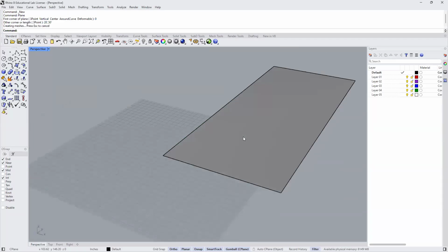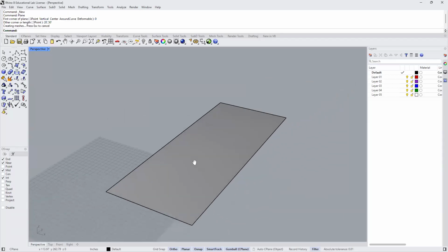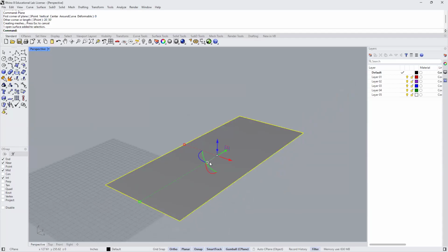And then I'm just going to zoom out and then hold down the shift, click and drag the right mouse button so I can pan over. And that's roughly the footprint. Now, if you're going to make multiple versions, I would go ahead and take that one and make a copy of it somewhere else before you do anything else to it.